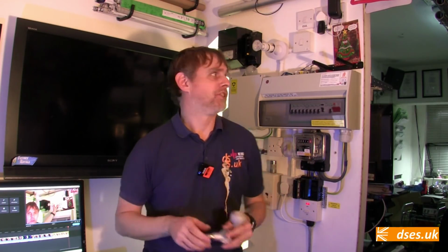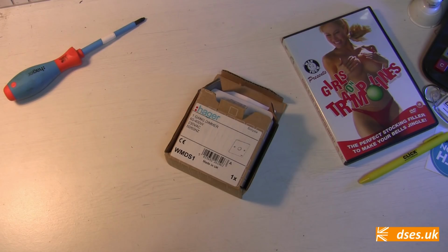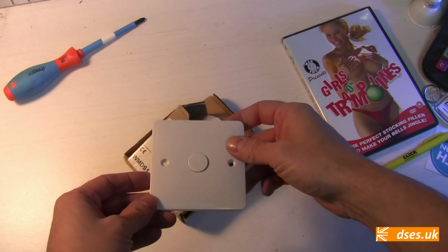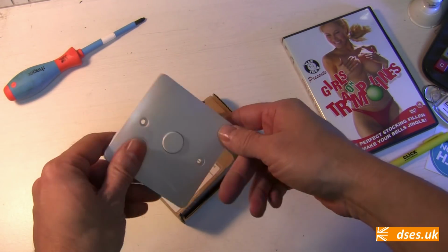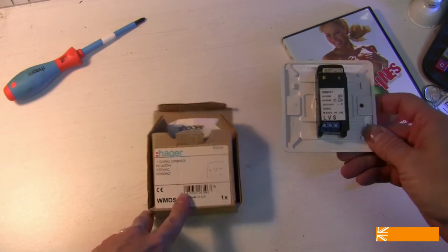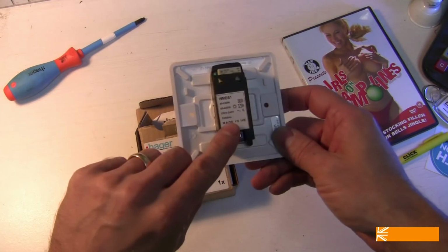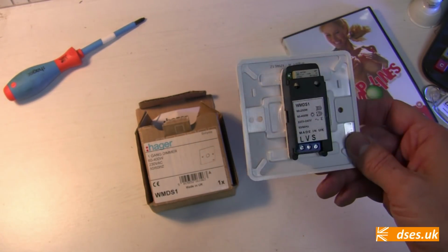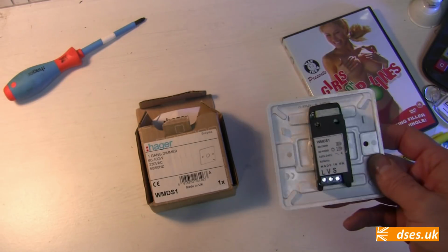But there you go, LED lamps need to be matched to smart switches or dimmers. Speaking of dimmers, problem number 3 is down to dimmer switches. A touch dimmer such as this Hager model, which controls the light electronically rather than via a mechanical push, may have a minimum load requirement, in this case 60 watts. And if your efficient LED lighting doesn't meet that load requirement, then you can expect gremlins on your lighting.